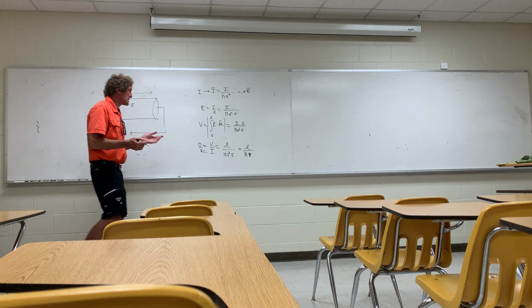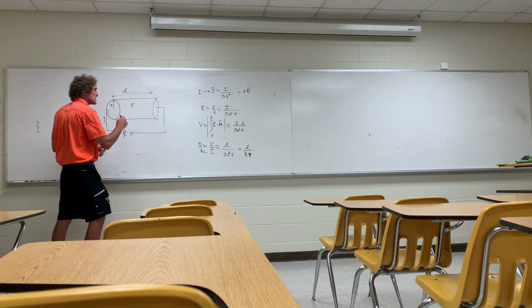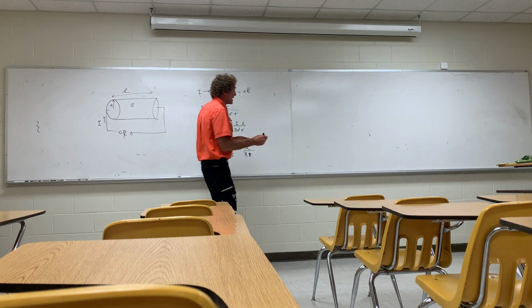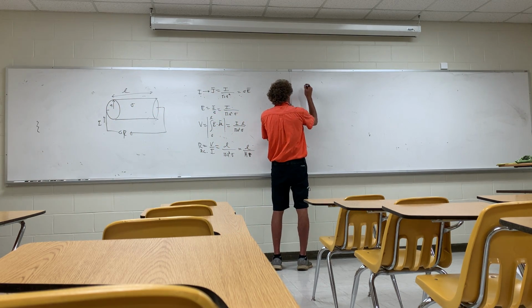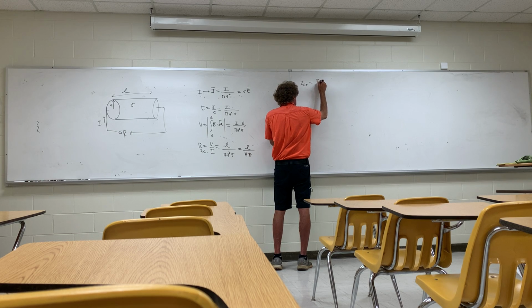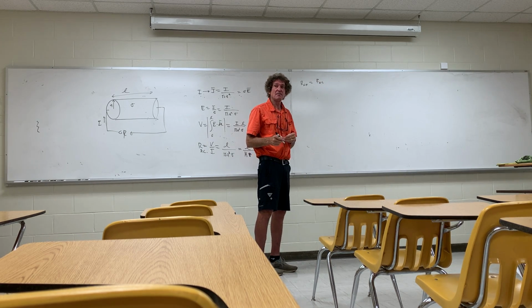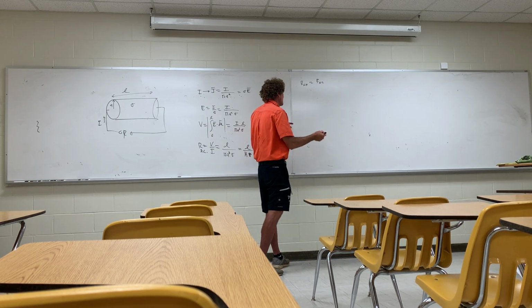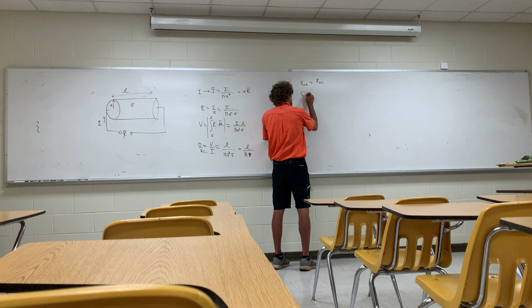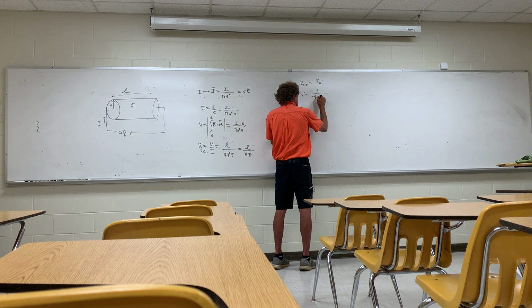Now, y'all remember when we said what skin depth did? Right. Skin depth caused all the current to hug the surface of the wire. And then you have what's called R, and I like to call it R high frequency. I think in Whitworth's book, Dr. Whitworth calls this R_AC. Now you're talking about when you have a time varying or alternating current that's high frequency. And the first thing you do is check the skin depth, which is equal to 1 over the square root of pi f mu sigma.